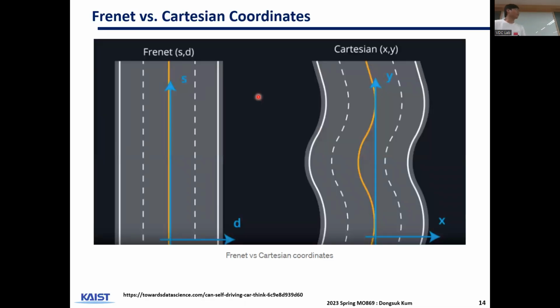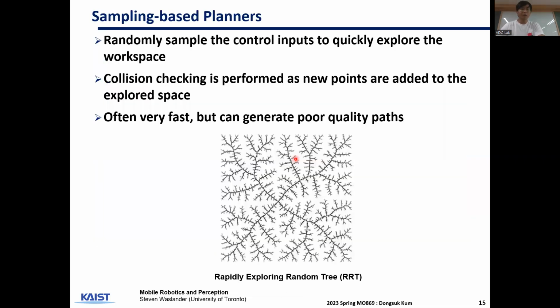The local planner is for the vehicle and its immediate surroundings, and is generally expressed within the Frenet frame coordinates, where roads are usually curved. In Cartesian coordinates, you simplify it by taking into account the curvature and then expressing it in terms of only lateral position information and longitudinal position information.